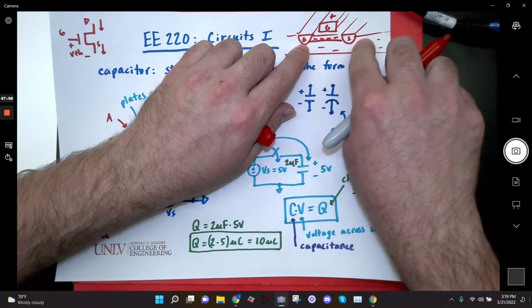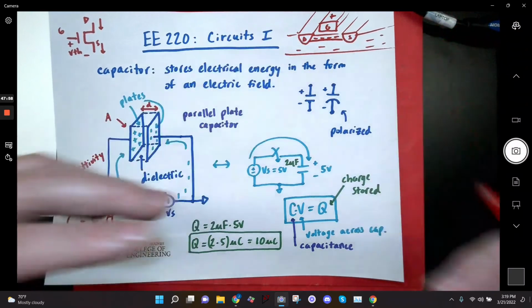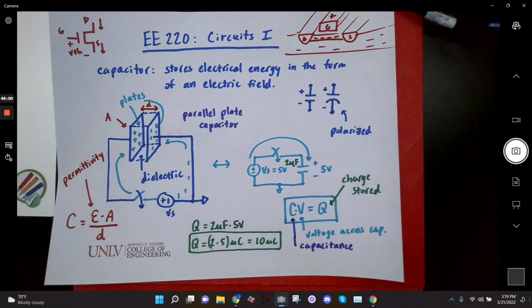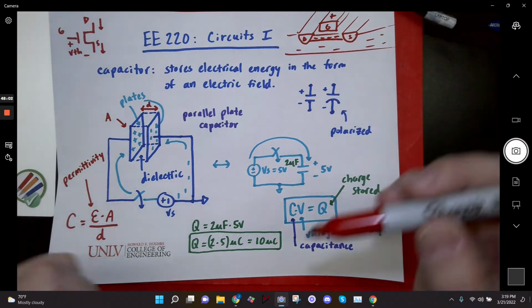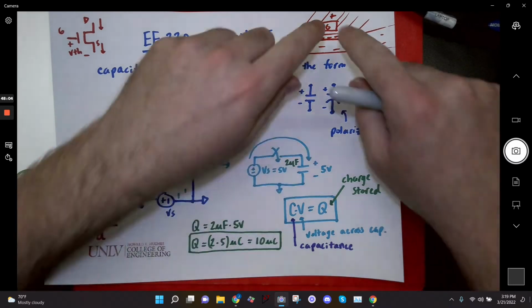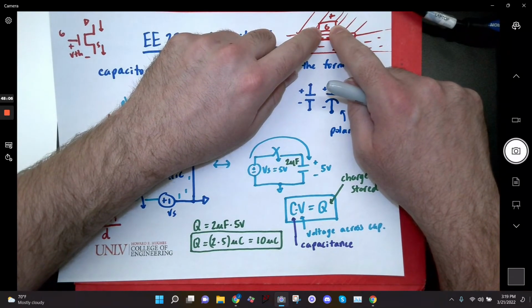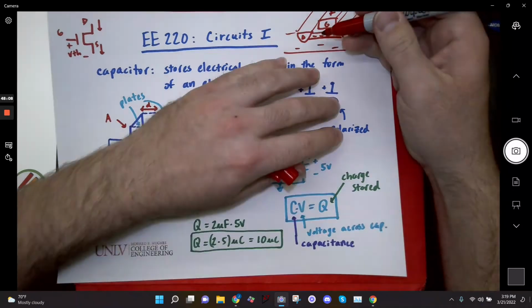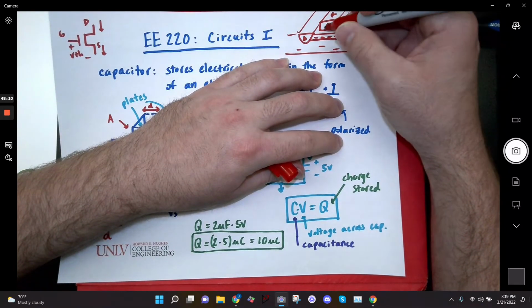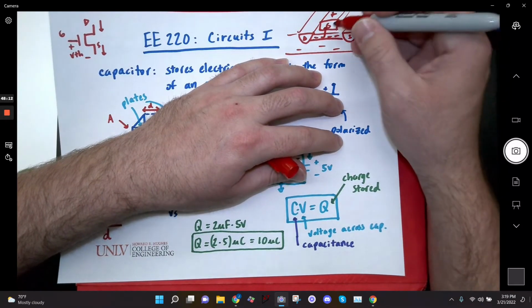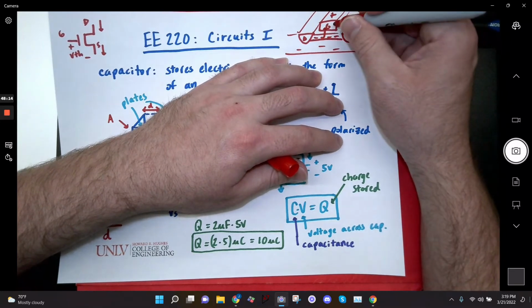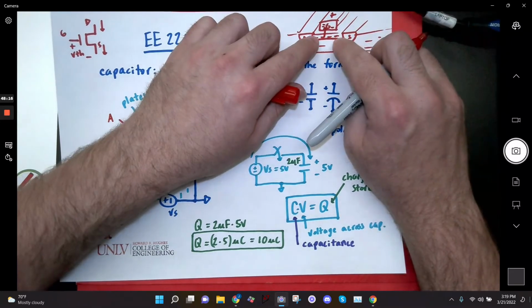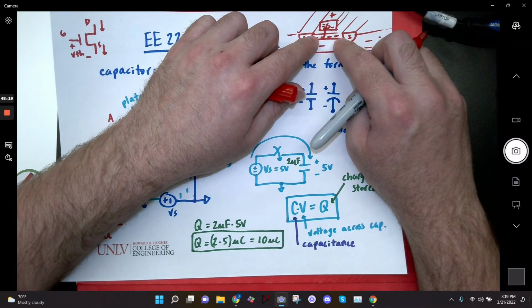And now current can flow from the drain to the source because I didn't have free electrons there prior. Okay? Well, what they do in flash memory is they'll put a gigantic voltage on this gate, so large that these electrons don't just get pulled under the gate, they actually get yanked through the silicon into the gate. And now you have electrons sitting here that repel electrons. Okay? Because electrons repel each other.